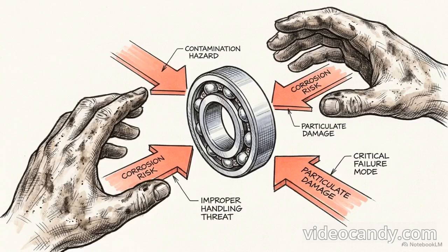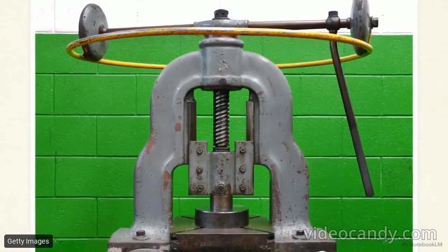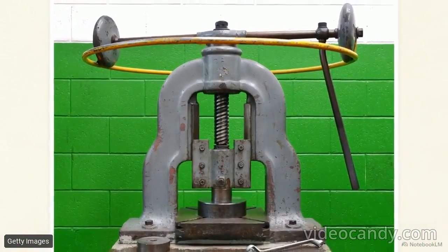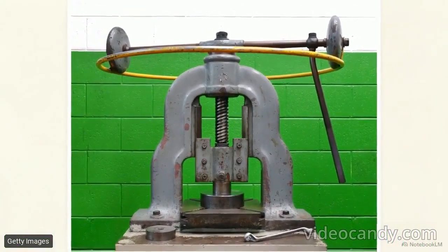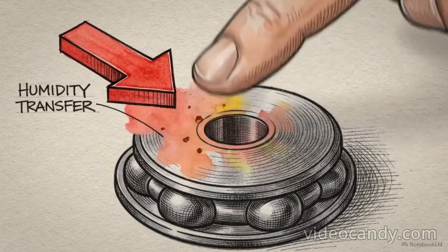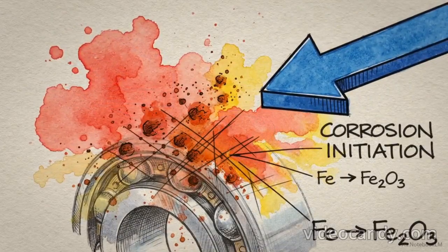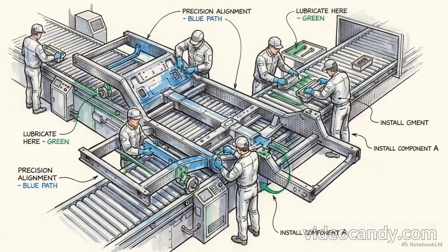against dirt. Even with perfect lubrication, the physical act of mounting a bearing can destroy it if strict handling protocols are ignored. Unmounting or seating a bearing requires specialized tools, like this manual arbor press. This ensures pressure is applied with perfect evenness, preventing distortion. The components are so sensitive that bare hands can be fatal. Perspiration leaves trace moisture on the steel, causing rapid rust and corrosive pitting. Brilliant mechanical engineering is instantly nullified if exact installation procedures and lubrication maps aren't strictly followed on the shop floor.